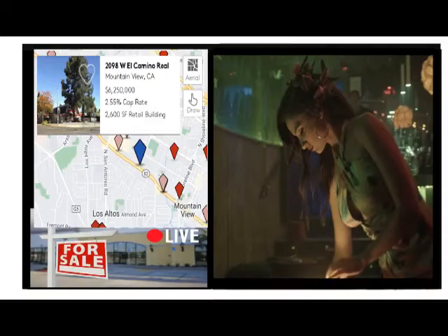Wiring in new homes. Telephone wiring that allows installation of two separate lines is becoming standard. Urban areas now offer the advantages of fiber optic cable connections to take maximum advantage of internet services. Although 110-volt electrical service was once the norm, the electrical system of a house built today should be wired for 240-volt service to allow use of the widest range of appliances.